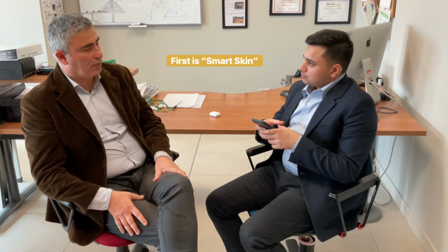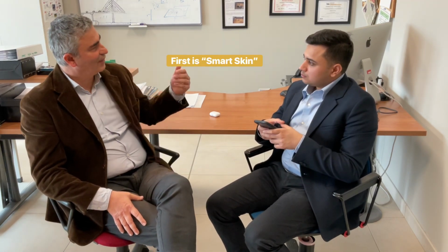Yes, obviously, if you increase the complexity, you have, as you mentioned, the repeaters, active RIS, and so on. But if you want to lower, for instance, the complexity and the energy consumption, and also avoid some of the limitations of RIS, we can consider, for instance, the smart skin, so basically completely passive RIS, or static metasurfaces, which are not reconfigurable. These are often called smart skin because they are supposed to be deployed like a sort of poster or paper on walls and so on, at very, very low cost.